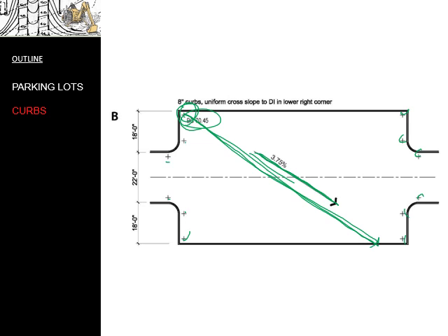And I'm pointing this out. It will not hit that corner right there at the other end. What you will do is you will use that line to solve for every one of these spot elevations. And one of the ways that you will do that is you will recognize that any points that are at 90 degrees to that line will be the same elevation as they are on that line.